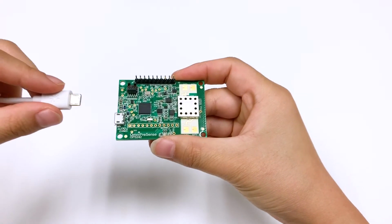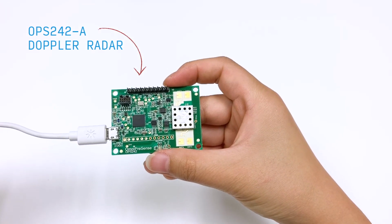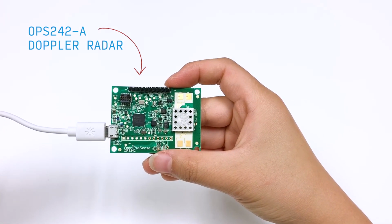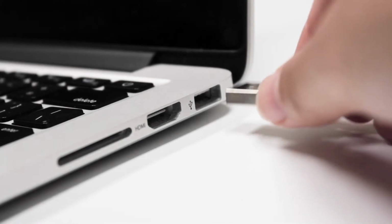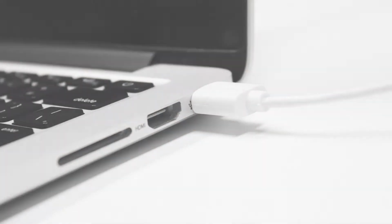Now that we've looked over our radar sensor, let's power it up and try it out. Step 1 is to connect a USB micro to your sensor. If you were going to use the UART interface, you'd connect the 5V power, ground, and TXD and RXD lines. Then we're going to connect the sensor into the USB port of your PC or Mac and start a command